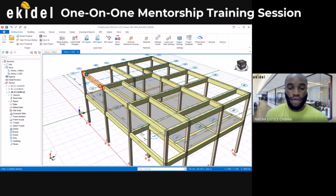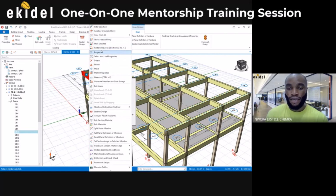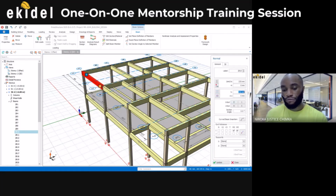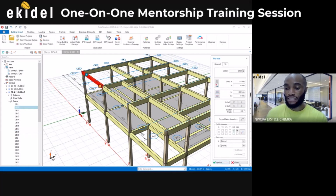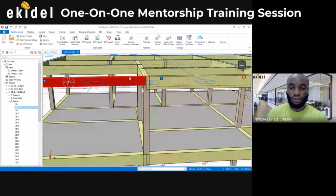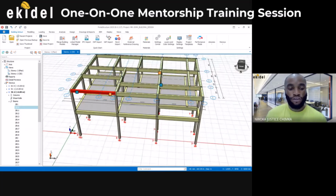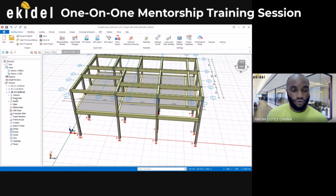So with that now, we also reduce this beam depth at once. I'll be doing them one by one. That will take time, by coming here and then saying properties, and then coming here and reducing by 300 and saying update. That will take time. You can see that now we have just reduced this one, but that will take time because there are so many. So we can do all at once by coming here under your story 2 now.